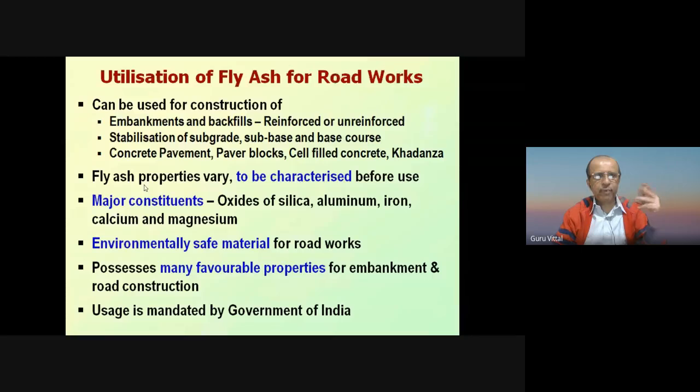Okay. So fly ash properties vary and have to be characterized before use. That is nothing special. Actually, properties of all construction materials vary. Soil also, aggregates also. What do we do? We test the material, and accordingly we design our structures. In a similar manner, fly ash properties will also vary.